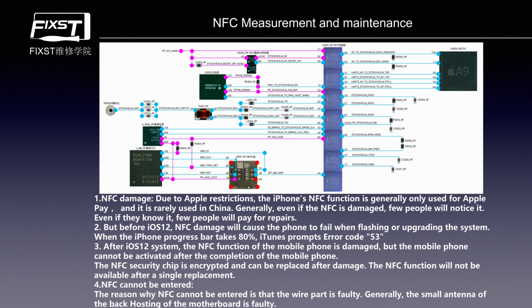With the NFC problem after the iOS 12 system, the phone can also pass the flash, but after the flash it cannot be activated. The NFC IC is encrypted. If it is damaged, we can change a new one, but after that the NFC function cannot work.